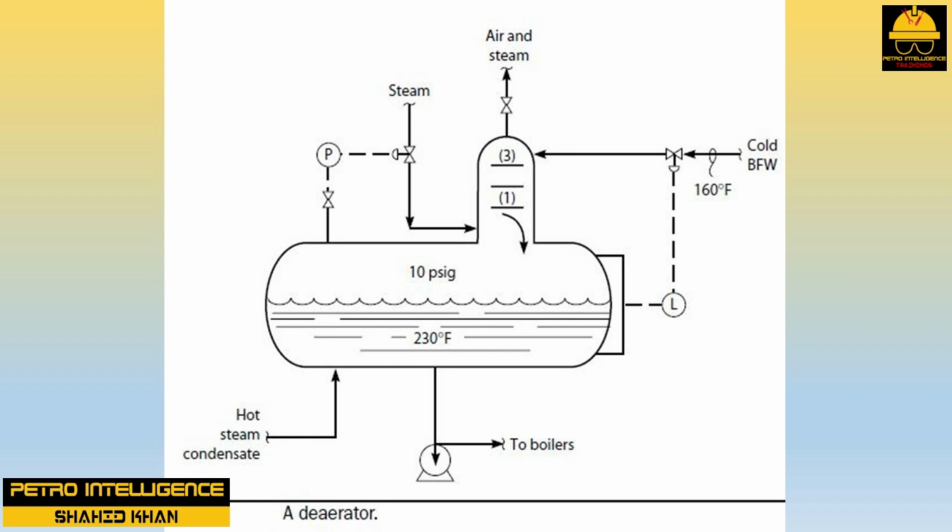The stripped 230 degrees Fahrenheit BFW drains into the large deaerator drum. This drum simply provides residence time for the high-pressure BFW pumps, which supply water directly to the boilers. Recovered steam condensate, which should be air-free, is fed to this drum through a separate nozzle.